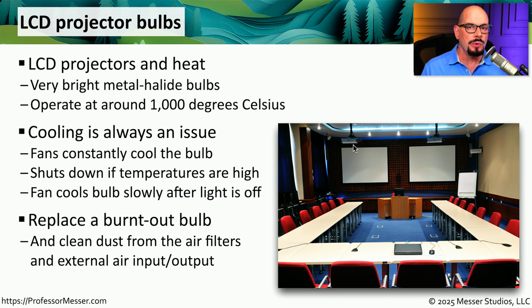If someone is going through the process of replacing the bulb, especially if these projectors are ceiling mounted, you might want to spend some time cleaning all of the dust and replacing the air filters inside of these systems. This will ensure that you have plenty of cool air that is able to be pulled through this projector and is able to keep that bulb as cool as possible.